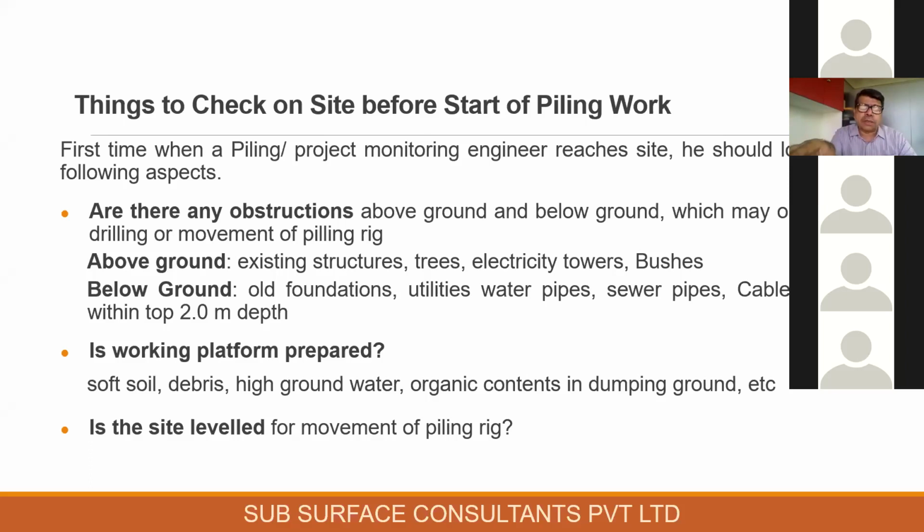We had an occasion near the Priyadarshini building where we had to make allowances for MGL's buried pipeline, and we had to wait till that pipeline was shifted out. That was somewhat deeper. So, though I have said top 2 meters, somewhat deeper pipelines may also exist.